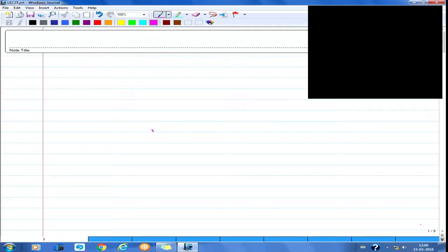So depending on the shape of the element, automatically the final expressions for x and y reduce accordingly. So even if the initial assumption is quadratic, the final expression would come out as linear in xi and eta only.